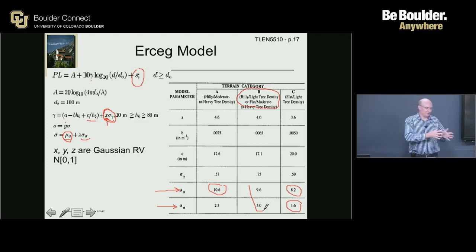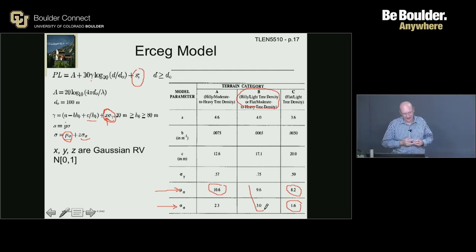It's an excellent question for higher frequency. 802.11ad and WiGig at 60 gigahertz is very concerned about that. A room full of people is a very different environment than an empty room at 60 gigahertz. And that starts to be well understood indoors, but think about now the 5G outdoor and what we talked about, all those frequencies above that. It's not well understood. So there's certainly room for research and improvement in an outdoor model considering people and other things in the way, more than just trees.